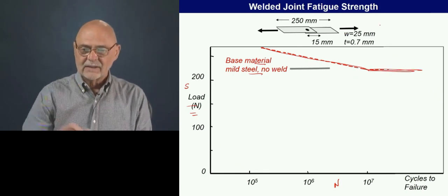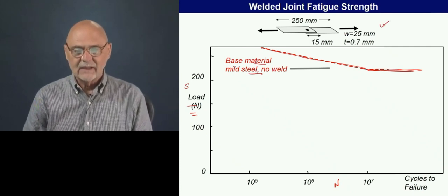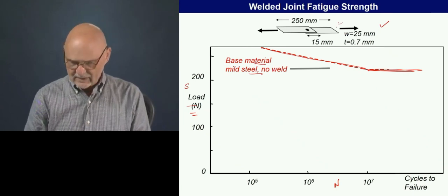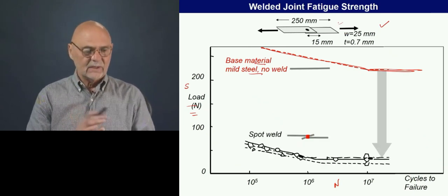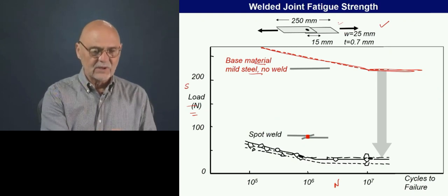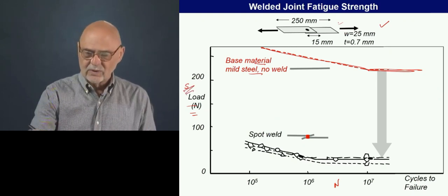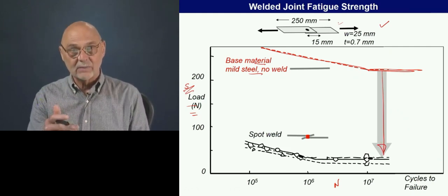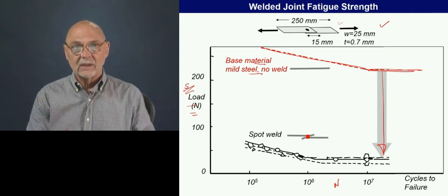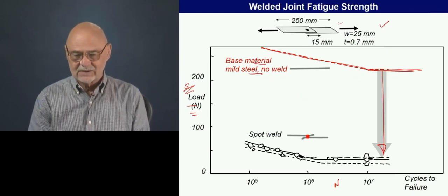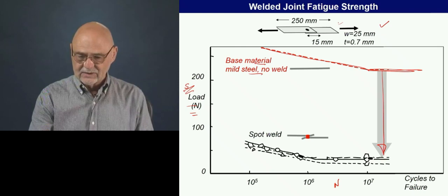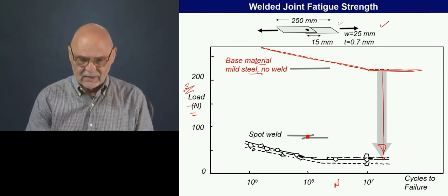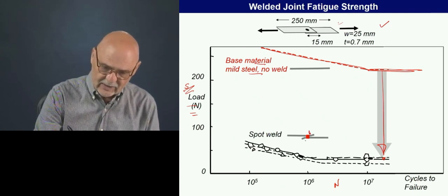Now if we take that same little specimen, about 1 inch wide, and do a cycles to failure curve here, we've really dropped down a huge amount. So this is where that factor of 10 or so that we looked at before comes into play: the actual stress where this little joint is going to fail is about 10 times more than the nominal value. So that'd be right here and right there.